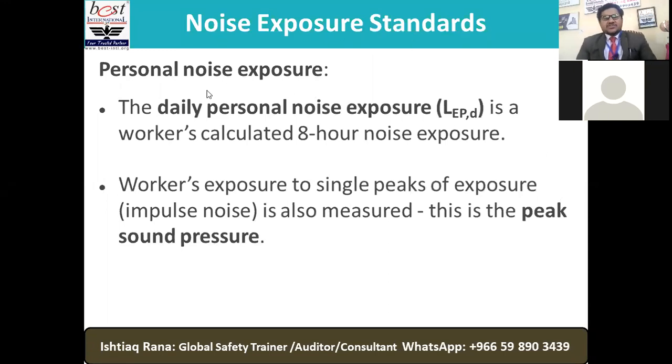Now, the noise exposure standards, personal noise exposure. The daily personal noise exposure, like LEPD, is the workers' calculated 8 hours noise exposure. Workers' exposure to single peaks of exposure, impulse noise, is also measured. This is the peak sound pressure.